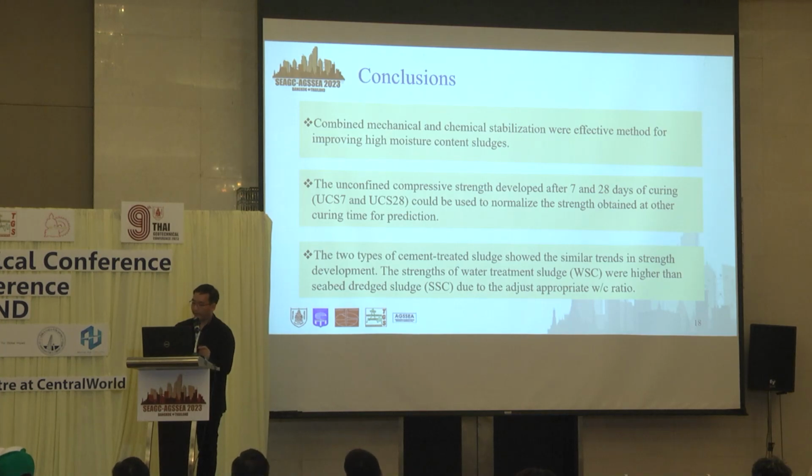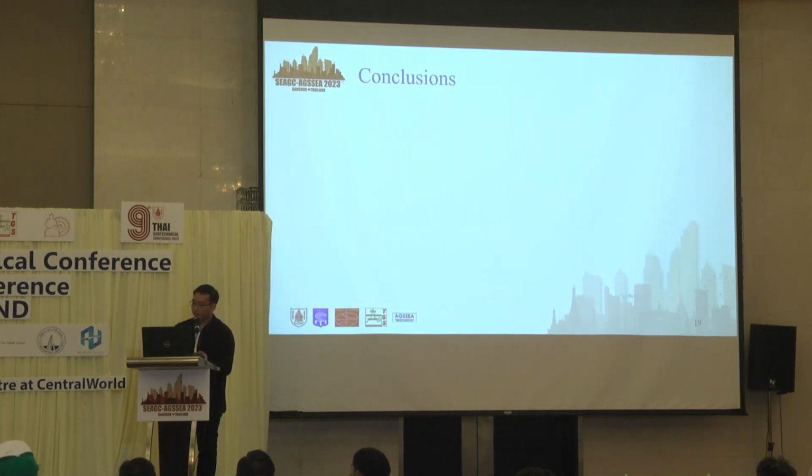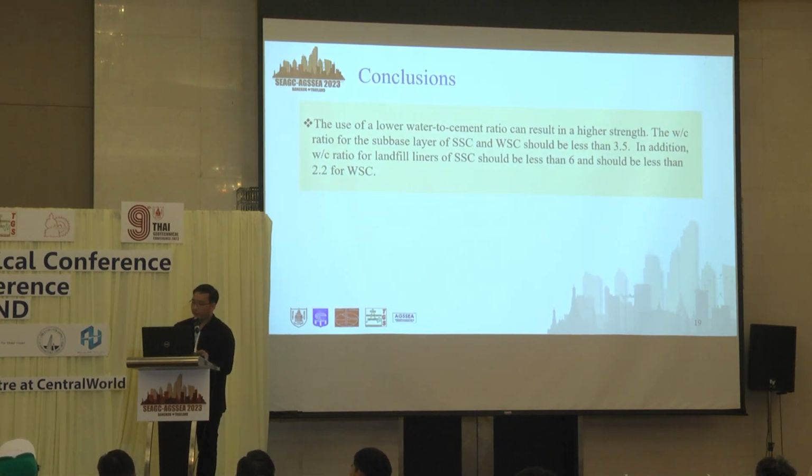The strength of WSC was higher than SSC due to the appropriately adjusted water-to-cement ratio. The use of a lower water-to-cement ratio in the same material can result in a higher strength. The suitable water-to-cement ratio for subbase layers of SSC and WSC should be less than 3.5. Moreover, the water-to-cement ratio for a landfill liner should be less than 6 for SSC and less than 2.2 for WSC.